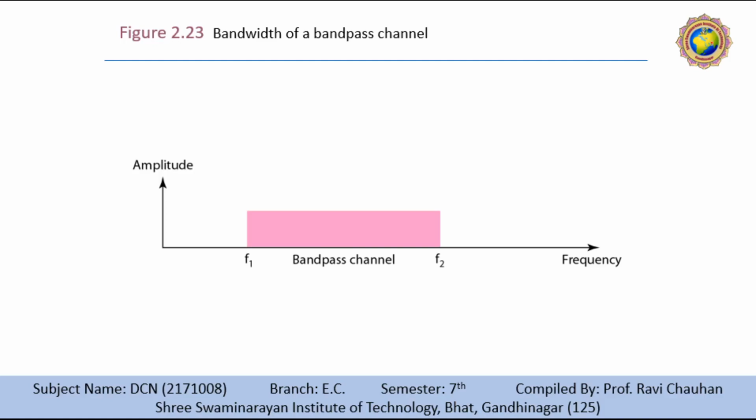Second is broadband transmission using modulation. Broadband transmission, or modulation, means changing the digital signal to an analog signal for the transmission. The modulation allows us to use a bandpass channel, a channel with a bandwidth that does not start from 0. And this type of channel is more available than the low pass channel. The figure shows the bandpass channel, which means it does not start from 0.